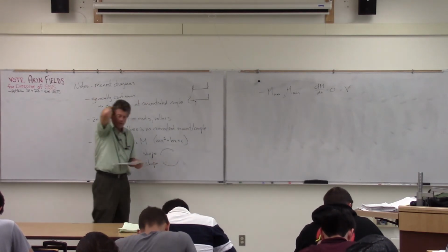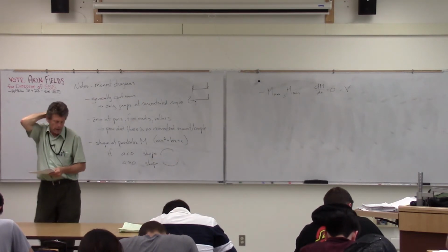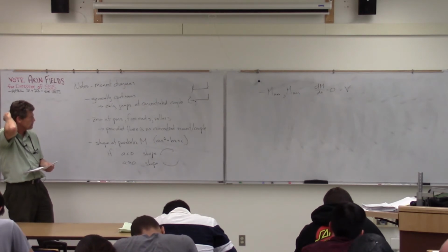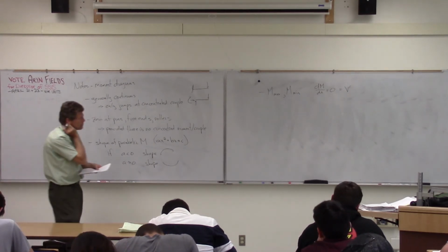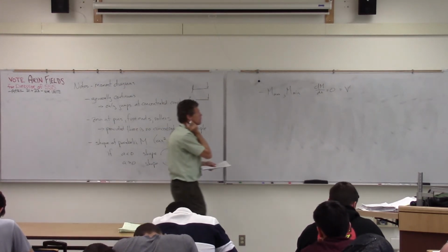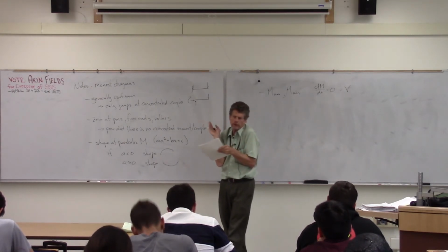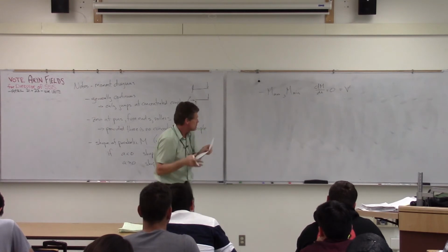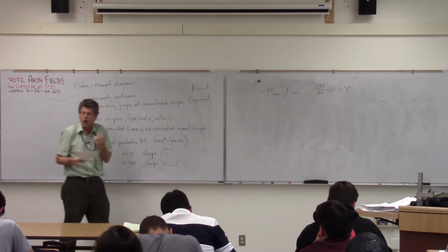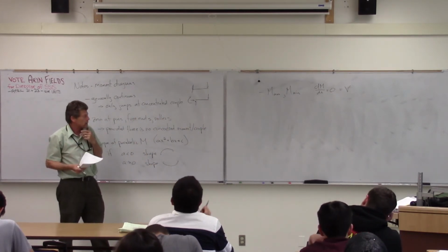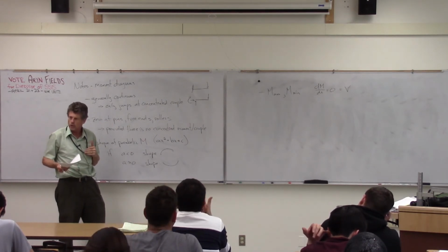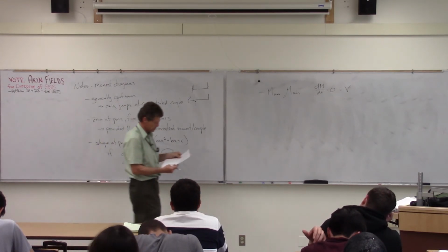Is we'll be looking for a min or a max of a parabolic or even a cubic at the point basically where the slope goes to 0, or as we saw looking at the equations, it's basically where the shear goes to 0. So when you draw your shear diagram and it goes through 0, that implies basically the slope is changing. We'll see why that is on Thursday.